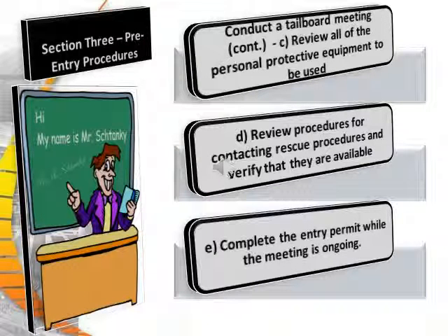When conducting the tailboard meeting, review all the personal protective equipment about to be used, review the procedures for contacting rescue personnel, and verify that they are available. Complete the entry permit while the meeting is ongoing.